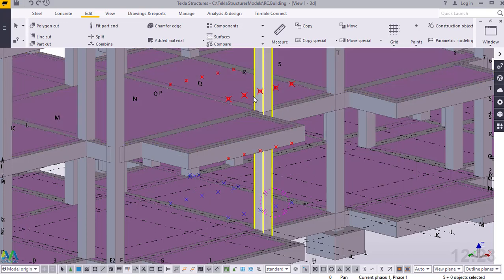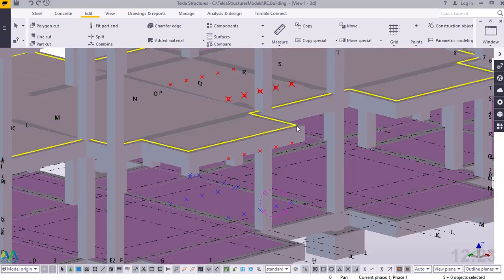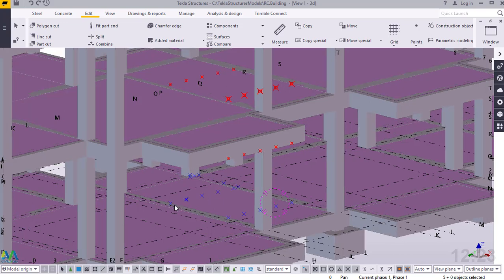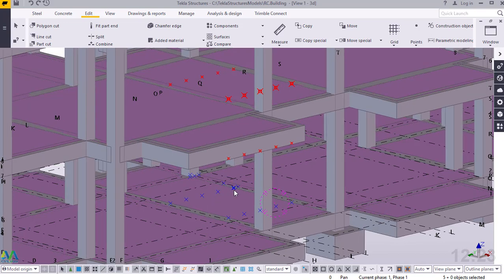So the critical points that we'll be using are these 2 points, these points, this one, and the ones down here. These are the most important points that will be assisting us in creating the staircase. Once those points have been placed in their appropriate location, we'll go ahead and start placing the RC concrete. And to do that, we'll go straight away to this applications and component button here.